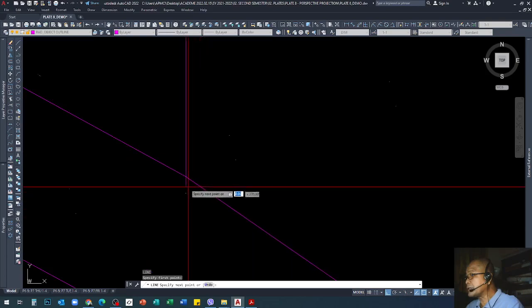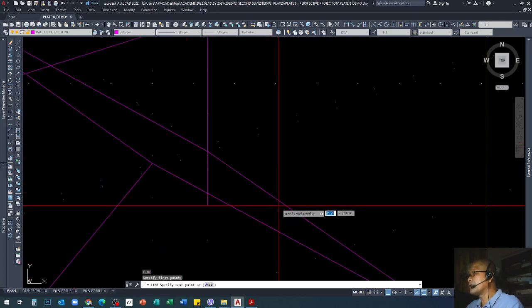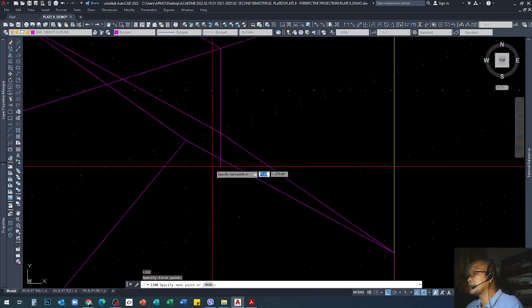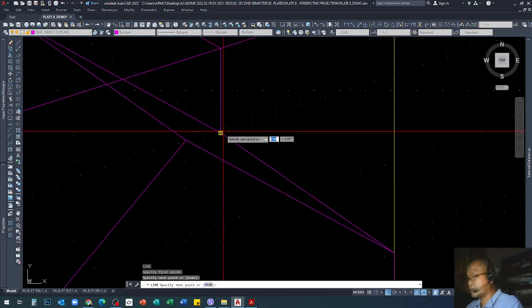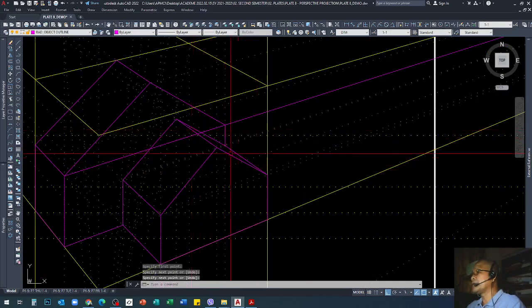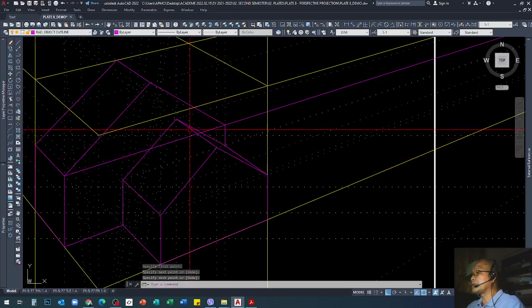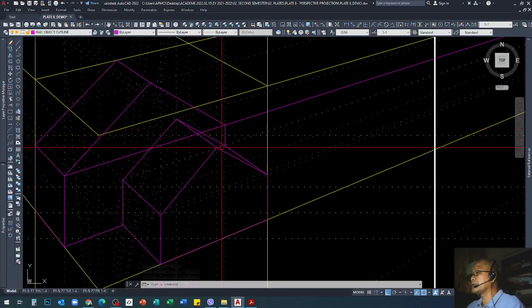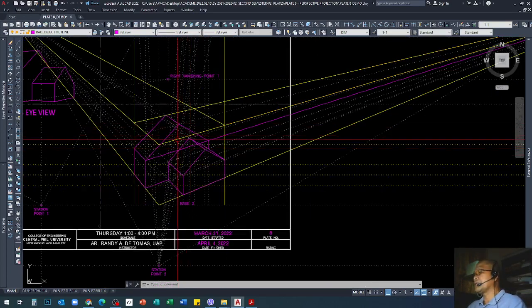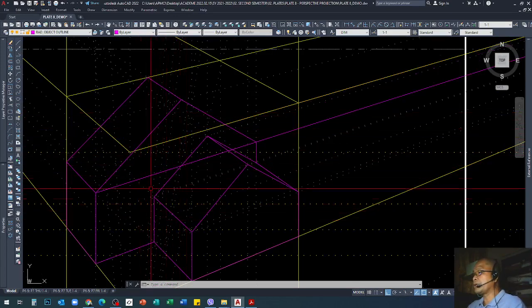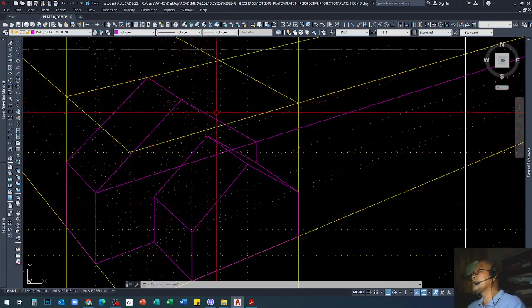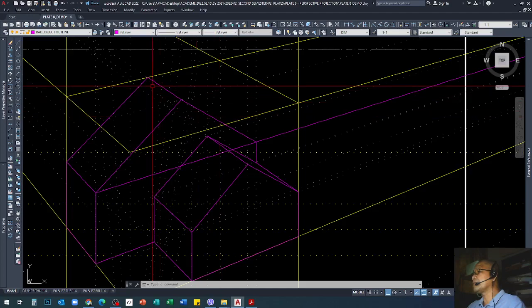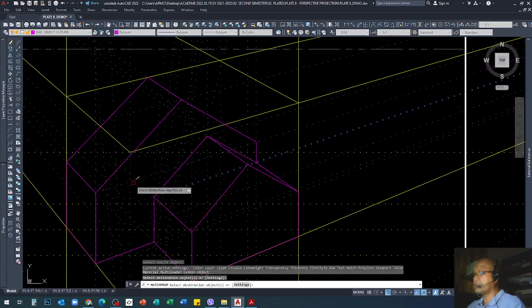As you can see, it connects to the corner of this lower projected inclined line. So basically we have done the front surface, so we need only to establish the back portion. This one, I can change these properties to dotted line.